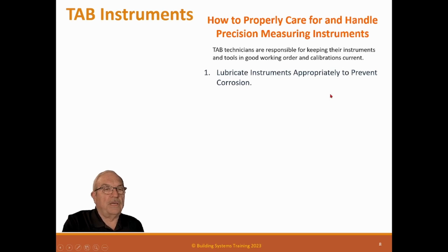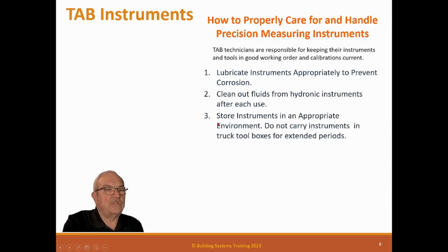So you need to lubricate instruments appropriately to prevent corrosion. You need to clean out fluids from hydronic instruments after each use. You need to store instruments in an appropriate environment. Do not carry instruments in truck toolboxes for extended periods. They need to be on the seat, somewhere that a human being would do okay. Don't carry them in the back of the truck. I've seen control technicians want me to use their electrical meter that's been in the back of the truck for 10 years, all beat up, scarred up, never been calibrated. And we say, no thanks, we'll use our own.